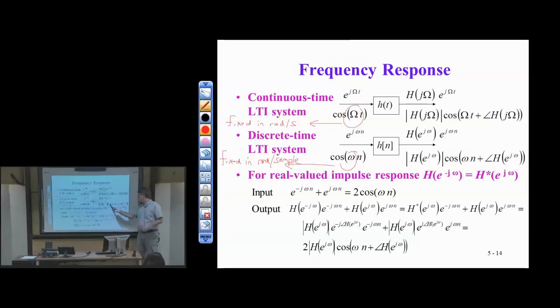I can look at the output and directly read off the change in magnitude and the change in phase. I can put in pi over 4, put in 0 for the DC response, and I can build up samples of the frequency response, both in magnitude and phase, and I can just interpolate between the points to get an estimate of the magnitude and phase response. And this is what we're going to do in lab. This is lab 3, coming a little bit later.